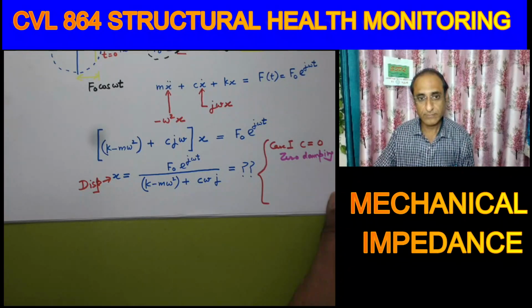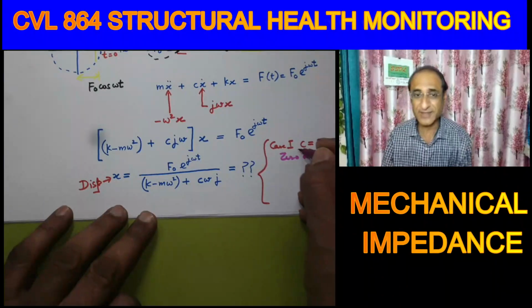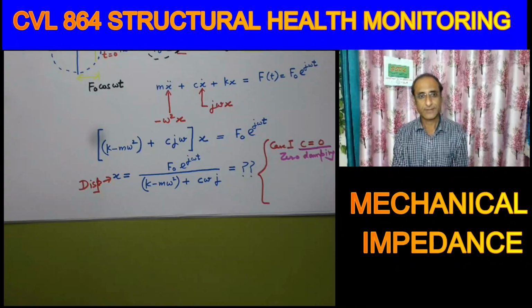Sir, there will always be a phase difference phi, and I think tan phi is equal to 2 r epsilon by 1 minus r square, something like that. See, if your imaginary part is 0, yes, any other guess? It will be in phase because only the constant term is changing. The angle is not changing. So according to you, if we make this term C0, in that case there won't be any phase difference between displacement and force. Yes, only amplitude also. Yes, correct.